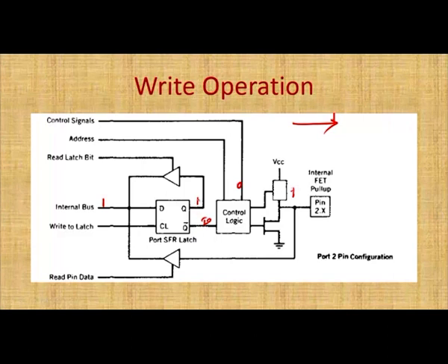Now, I am giving the value 1. So, 1 means because of the D latch it simply passes it as the output. Okay. And also the Q bar value is 0, because it is a characteristic of the flip flop, 1 and 0. So, if you are giving 0, here I naught is selected. So, it simply passes the I naught to the NMOS. So, this NMOS, what will happen? It goes to off state. Once it is off, only the VCC value will come. So, it will get the value of 1. So, you are writing the value 1 and also you are getting the value as 1.